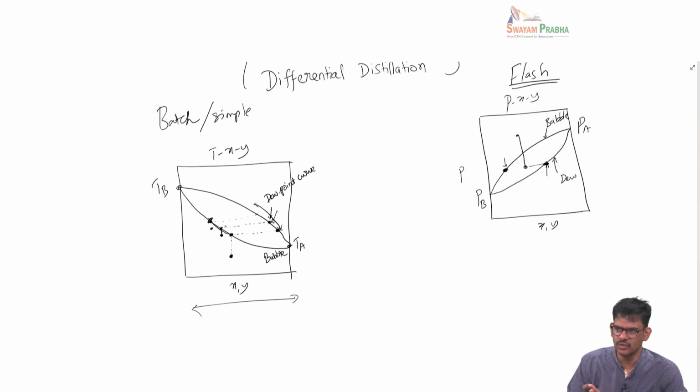So that's why it actually goes a little bit away from the bubble point, but then you're constantly applying heat. Yeah, so if it's an azeotropic mixture, the two curves will be the same curve, right? The two loops will actually converge into the same line. Okay, so then when you vaporize, the vapor and the liquid have the same composition, right? So no matter how much vapor you take away, the liquid will always have the same composition.